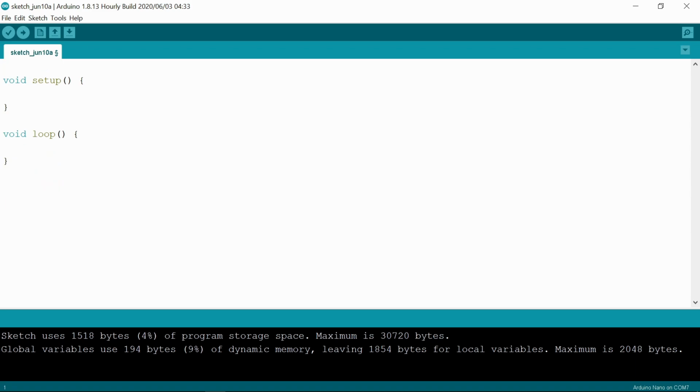Let me show you a simple example Arduino program. Let me set a global variable. I have set my global variable C with the value 13. You can see here the pinMode function within the setup function, and that's the fun part of understanding Arduino. pinMode basically sets up a pin of the Arduino board for input or output purposes.